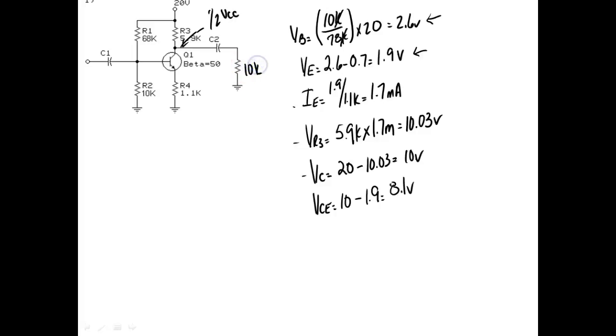So here we're going to load this thing. I mean, the book doesn't show you how to load it, but I wouldn't have an amplifier if I didn't get work out of it, right? Y'all understand that? So we'll come over here and we'll calculate, so the formula is AV would be equal to R out over RE, because it's not bypassed, right? So we got to calculate R out. So R out would be equal to what?